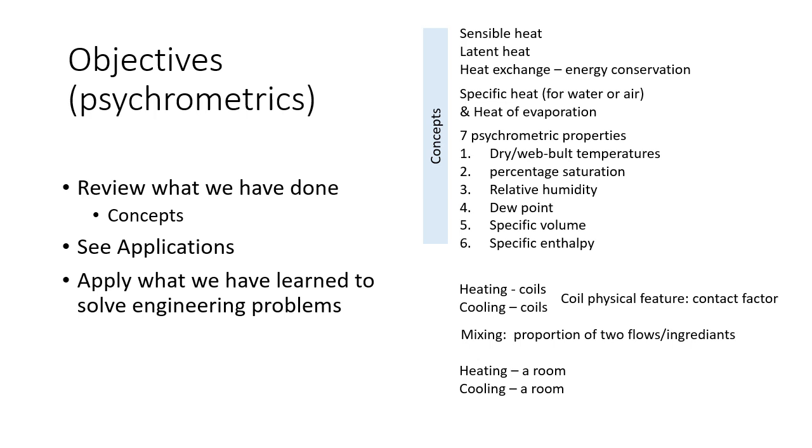If we do not remove that heat, the temperature in the room will rise, and we'll start to feel discomfort. To avoid the temperature rise and heat accumulation, we supply cool air lower than the room temperature. So the air goes into the room and rises to the room temperature. That is the process of absorbing heat in the room.